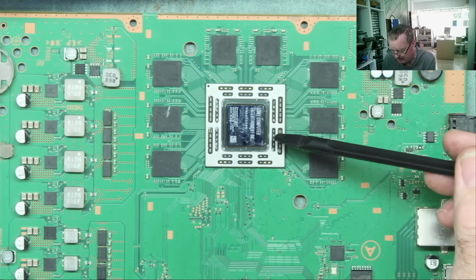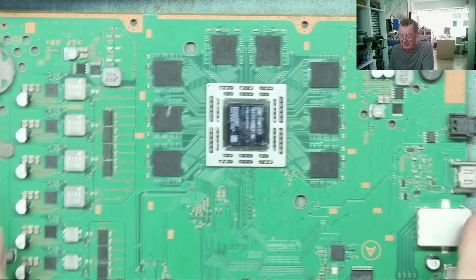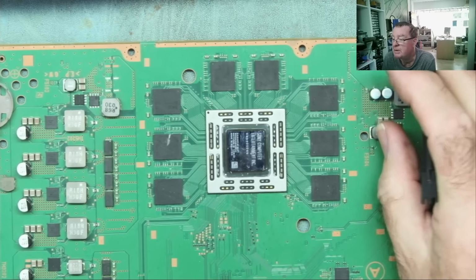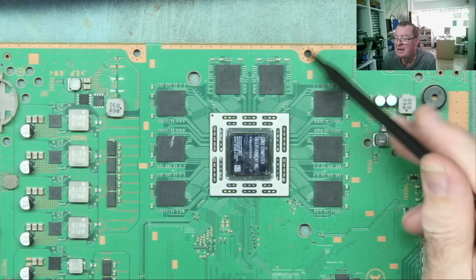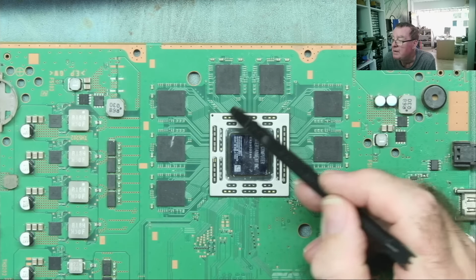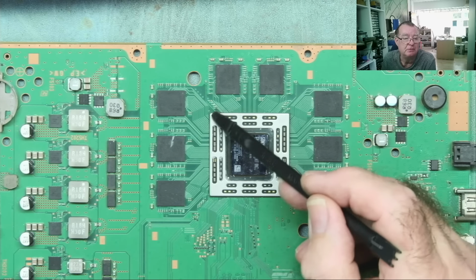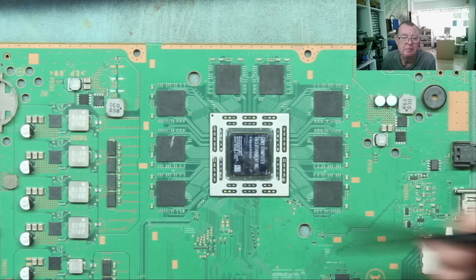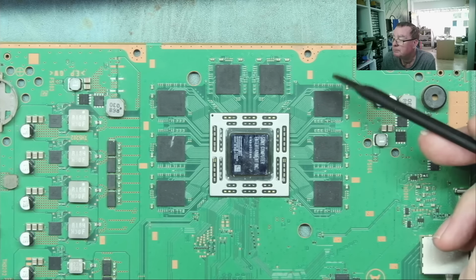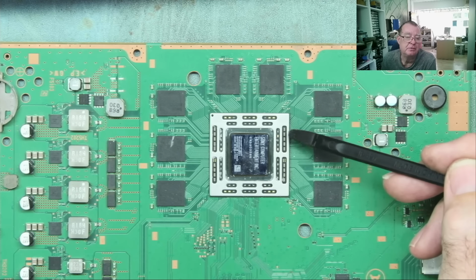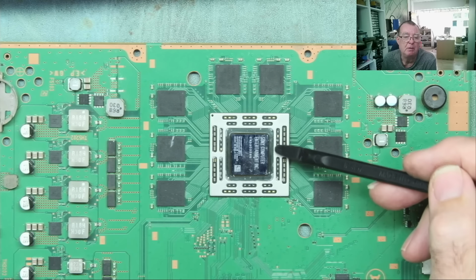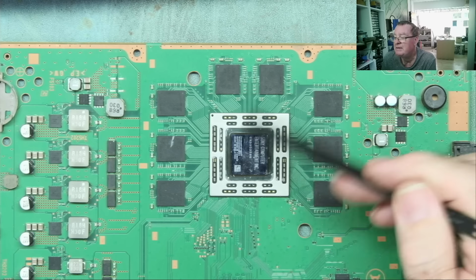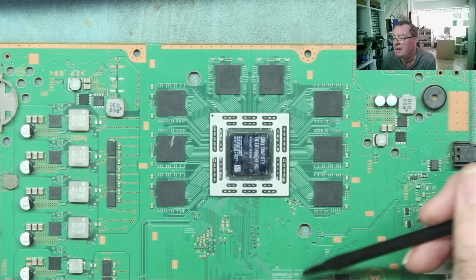This sort of failure may be intermittent, pushing hard down on the chip or flexing the board may cause the fault to come and go. It may be permanent. It can be difficult to diagnose exactly, and if they do fail, by the way, they tend to fail near one corner, I will mention. In the cases I've found this on memory chips, on BGAs, it always seems to be on one corner, the failure. Without the correct equipment and without the amount of experience you need to learn how to work on this, this is not something that you can easily repair, okay?